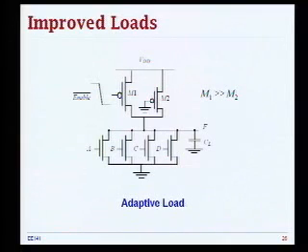You say, well, my transition has finished, so let me decrease the current that I need to fight from the pull-up. In that case, I have good static power consumption. But next time you need to go into the transient regime, you say, I'm going to enter turbo mode, I'm going to turn on this other device and pull up really fast. This is the idea behind active loads, where you can selectively enable or disable these transistors to play with the equivalent resistance of the pull-up network.